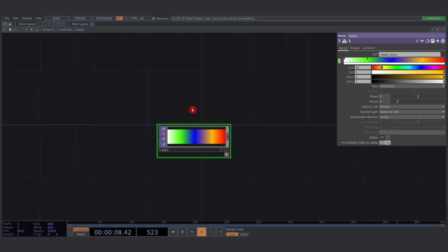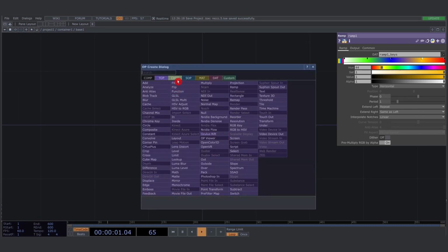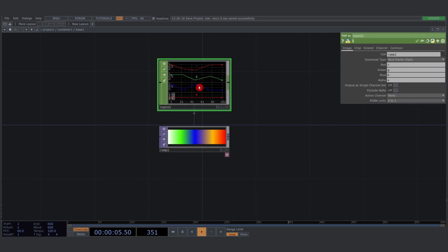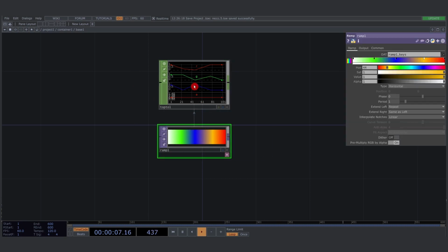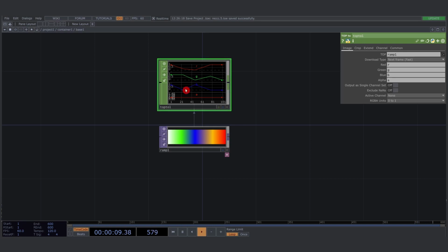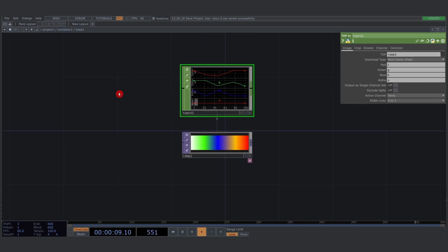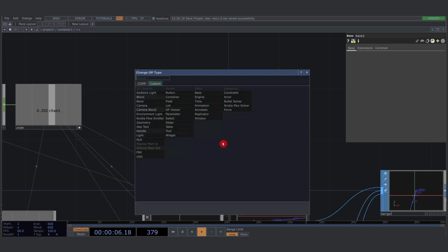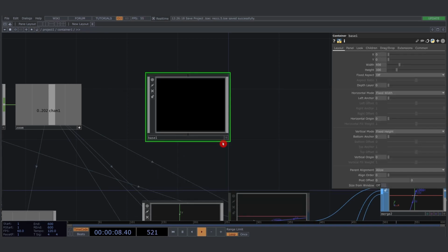So now we want to sample or click one of those colors and capture the color that we've clicked. For this we can normally convert to a CHOP, but here you see that everything inside of this TOP gets converted to its corresponding RGBA values, and we only need one of them. And now I realize that I've put this in a base, but actually if you right click this base you can change the type, as we want it to be a container.